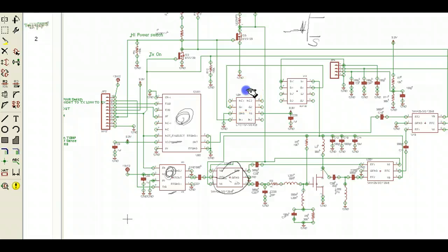This device here is what we call a high side driver, and what comes in here is digital signals. Somewhere along the line, this signal is going to be high or low, either 0 or 3 volts. If you put 3 volts on the input, this drives this gate signal to 7 volts. That 7 volts drives a gate over here, which controls some current. The nice thing about FETs is that when they're in the on state, they can pass amps with only a 100 or so millivolt drop.